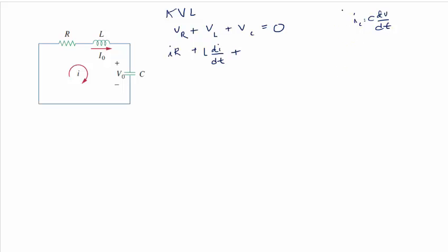So we need this voltage that's hidden, embedded in this differential. What we can do is integrate both sides of the equation. We'll integrate from negative infinity to 0 minus. Same thing on this side. If you integrate the left, you have to integrate the right. So we'll integrate both sides. We rewrite this a little bit. So the integral of I dt equals the integral of C times 1 dV, right?